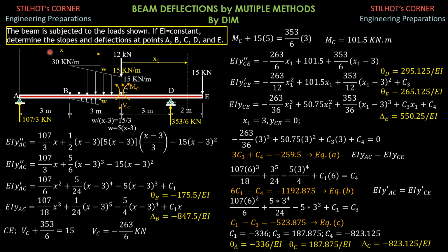Now, you may have one equation if you want to extend that, but I'll just present two differential equations, so that whenever you encounter a segment where the loading is quite complicated, and you can hardly express the moment for the entire beam as a function of one distance x from the leftmost end, then this is the idea.